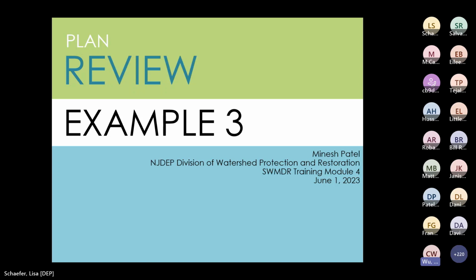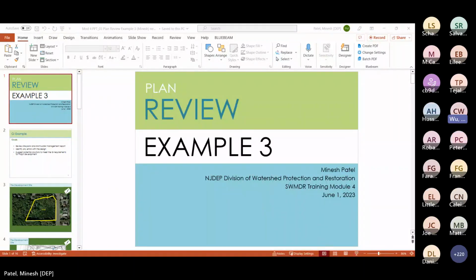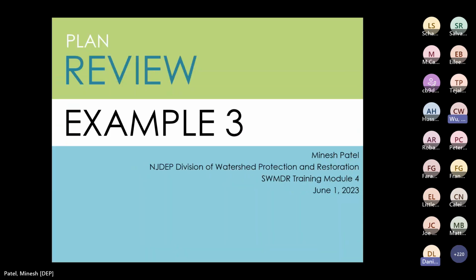In a very urbanized area, you may use a small scale retention BMP like a rain garden on the surface for water quality, and then direct the runoff going down to the underground infiltration basin, and have the storage underground, like under a parking lot. We have seen designs like that. So you can have that.